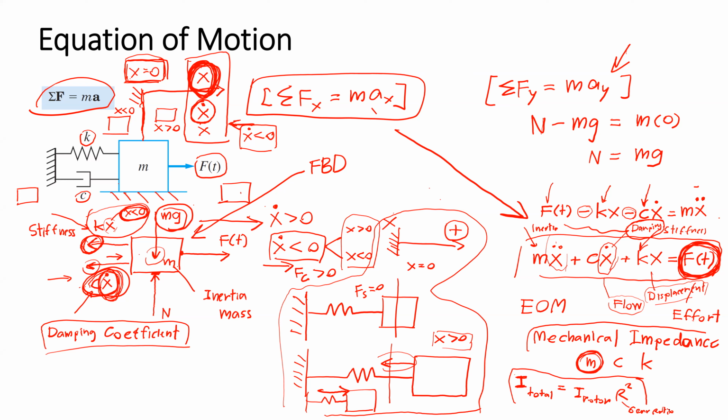For the industrial robot, if we want to obtain high torque, we use a high gear reduction ratio on the motor. Of course, we can get the amount of torque we want from the motor and gearbox, but the undesired property is the large inertia of the motor and gearbox. It can be good if the robot just moves by itself in a separate environment, but if the robot needs to interact with the environment or with humans, the high inertia is an undesired effect, because if the robot hits something, it can create big damage.